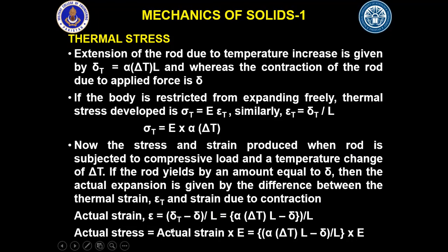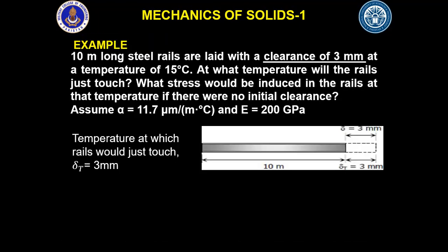Similarly, we can have the overall stress in the rod as well using the same equation. We are going to use the same equation multiplied by E. So it is going to give us the actual stress in the rod, which is going to accommodate the effects of thermal stresses as well as the applied load stresses.